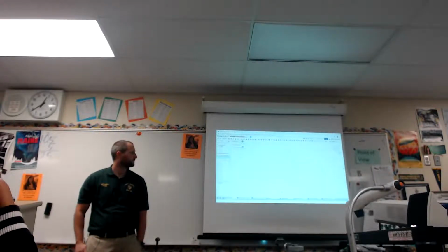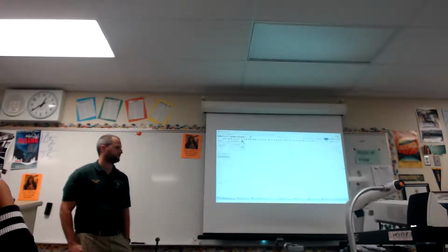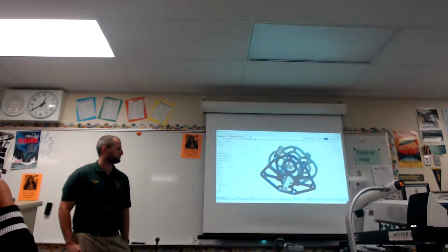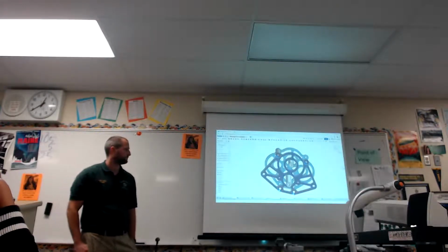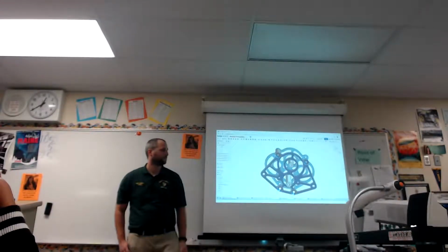And as you can see, once it loads up all the changes, pay attention to changes in the actual gearbox plate, because that's where they're going to be most evident compared to the previous version. There you go. So the first change is that all of these lightening holes, those holes cut out to make the gearbox lighter, actually change to match the new gear ratio.